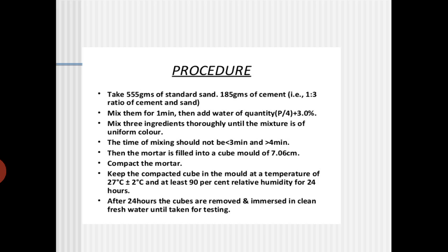After 24 hours, the cubes are removed and immersed in clean fresh water until taken for testing. This last point is very important, because we have to use clean fresh water only. You are not supposed to dip the cubes in muddy water.